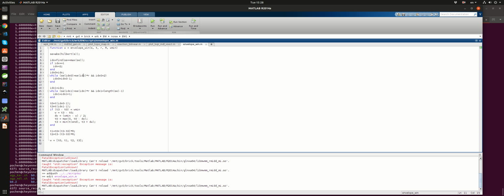Then it identifies the location of the peak, and goes from that peak backwards in time, trying to find the first point where the envelope amplitude reduces to small r. If small r is 1/5, the backward track stops when the envelope amplitude reaches 1/5 of the peak amplitude.